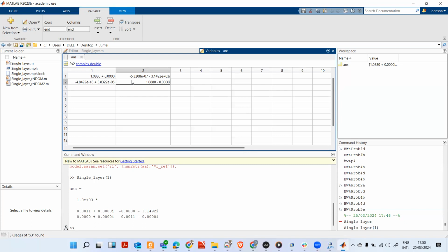Now, if you have a membrane instead of a bubble, across the membrane, again, the velocity, oh, sorry, my bad. For a bubble, the pressure is continuous on both sides, but the velocity is not continuous on both sides because some of the velocity is going into the bubble during the resonance.